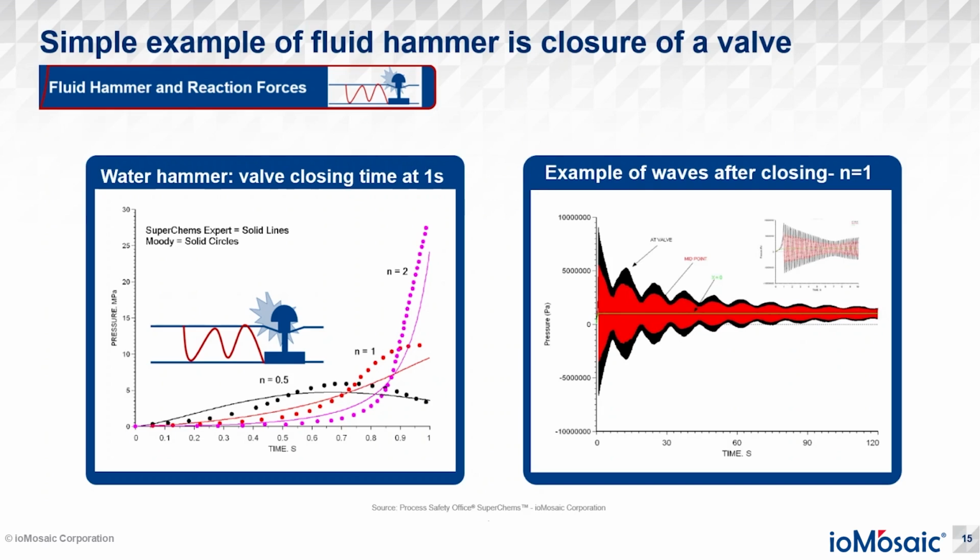And we can see here on the graph on the right hand side that the pressure waves are all kind of reflecting off each other. And you can see it's a bit coalesced at the moment. But the point here is that depending on your pipe lengths, you can actually get a lot of build up and interaction with the pressure waves going back and forth between the closed valve and the pressure source until it will eventually equilibrate and calm down. You can see it will eventually be very, very amplified, and then it will calm down as time goes on.